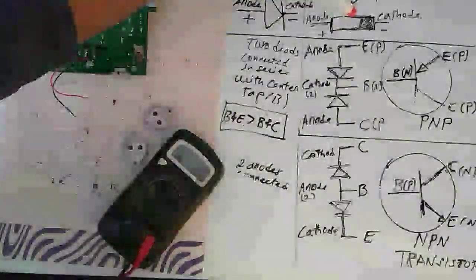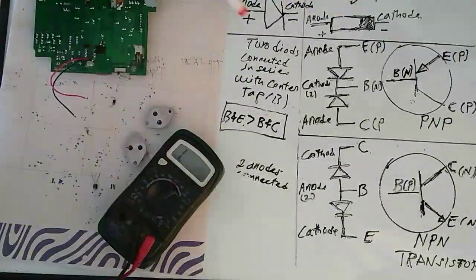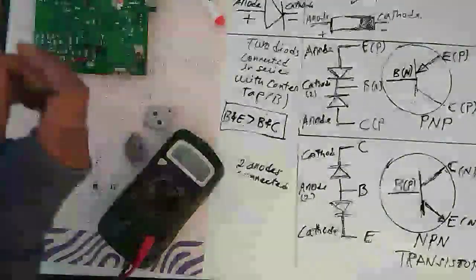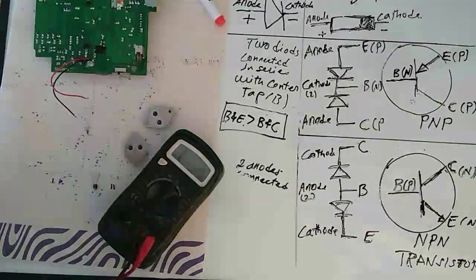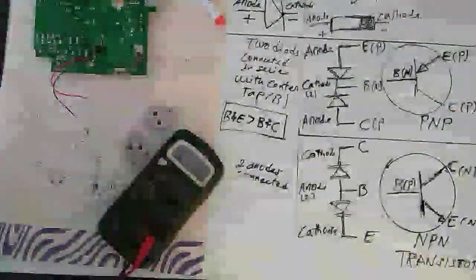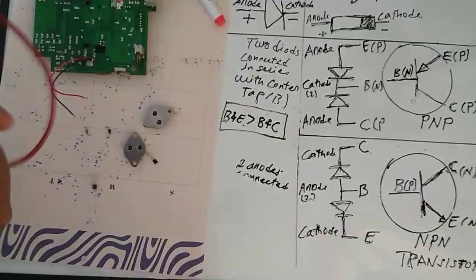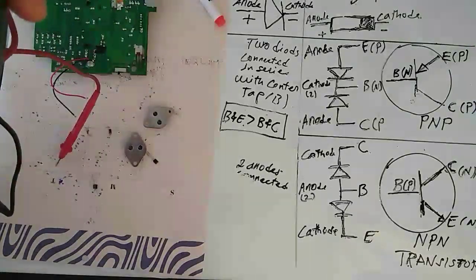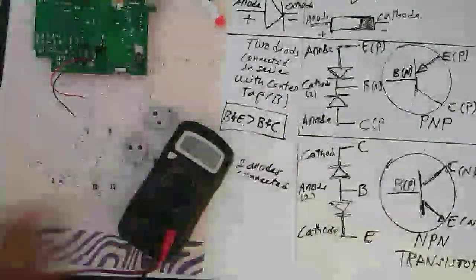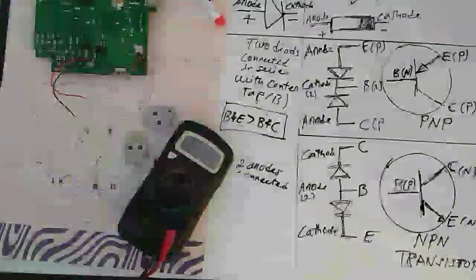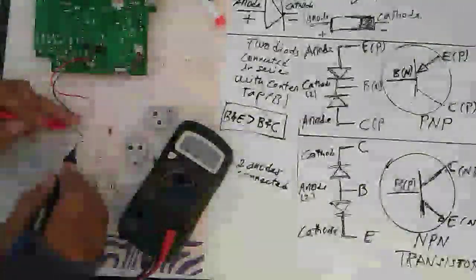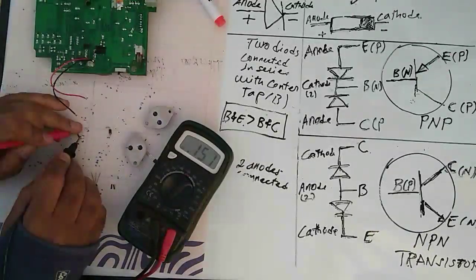This is the circuit diagram, and this picture shows the physical part, where the sign is over here. So we're going to measure that first, and first you have to put the multimeter at the diode indicator. First we're going to measure germanium.